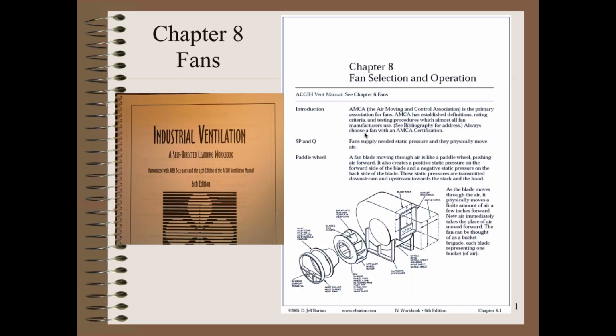Now you put a turn. That turn might add, how do you know what that is? Or how many sections is it? 90-degree turn. What's the radius of the turn? You look up on chart 5, I think it is. Not chart 5, chart 8, I forget. For elbows, 13. You look up, is it 13? Yeah, you look up K for the elbow, for a specific elbow, times the velocity pressure. Let's say that that's an inch. You lose 1 inch, right? So now you have to generate positive 1.5 inches to get it moving through, because that has to be positive because you're pushing from the fan, not sucking.